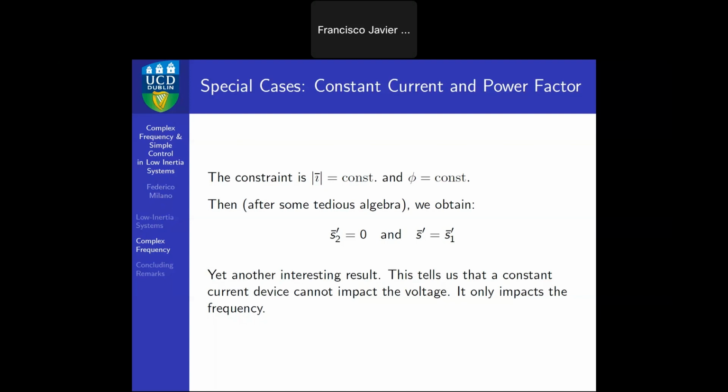So we can try to make controllers that are more efficient, just trying to minimize, if you wanted to do frequency control, minimizing P2 or Q2, depending on what you do. And then the other way around, if you want to maximize the effect of the voltage control, you need to minimize P1 and Q1. It's a completely different way of seeing it, but it's still based on conventional equations, right? It's not new, it's just the derivative of power flow, right? So it's just a consequence of it.